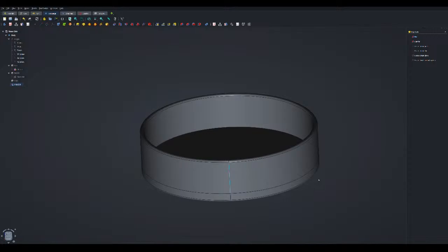Okay, then it's mostly the slicer's, what you're telling me. Yeah, so in your slicer, in the seam settings, you can tell it to have a straight vertical line, or you can tell it, on every Z layer, to start in a different random spot, so that for every layer the seam is in a different spot, so there's no singular defined Z-seam.